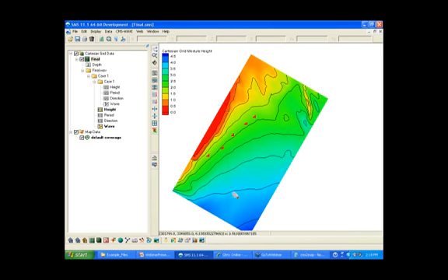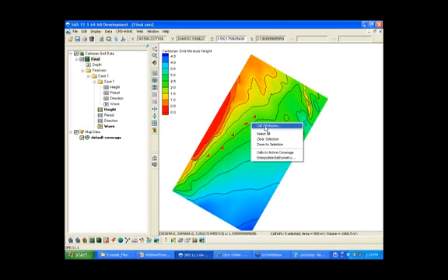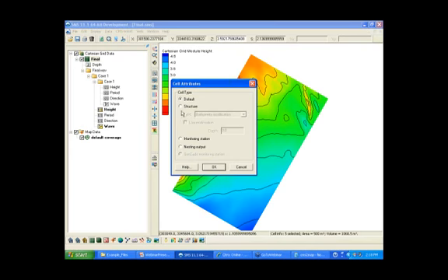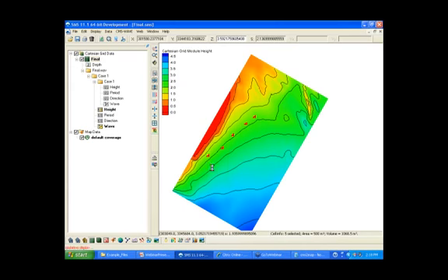This is a case where you can see that I've already chosen 5 observation stations, and we can add a few more. What we're going to do is go here and select the grid cell, and then left click wherever you want the grid cells located, and then right click on your screen, go to cell attributes, change from default to monitoring station, and then click OK.